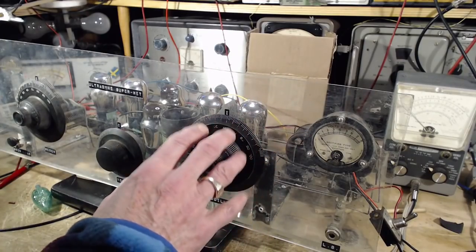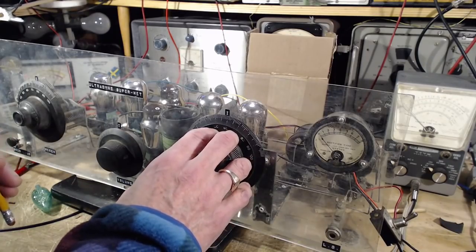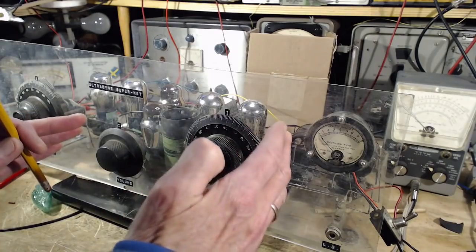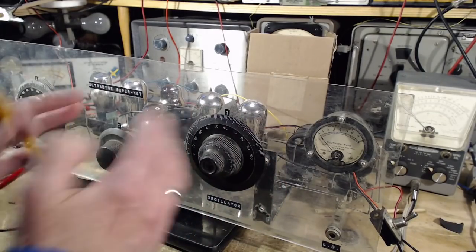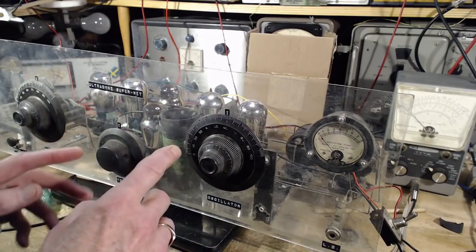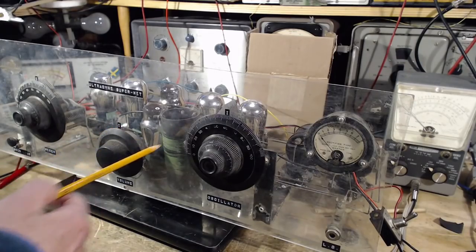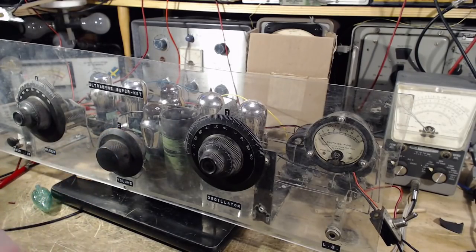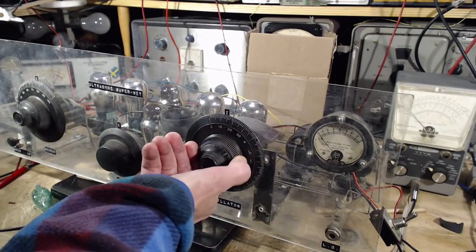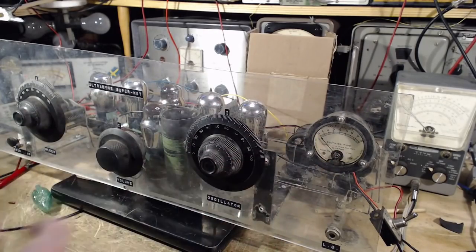So what I'm thinking is this resonance thing that I picked up with my SDR is really the resonance of the oscillator changing to change the frequency. But the oscillator is not oscillating within that resonance either. The Q of the resonance circuit's not high enough, or there's something wrong. I'm sure there's something wrong in here with the tube and the coil and that kind of stuff. That's the only way I can reason out why tuning this would show a tuned resonance traveling up and down the broadcast band.